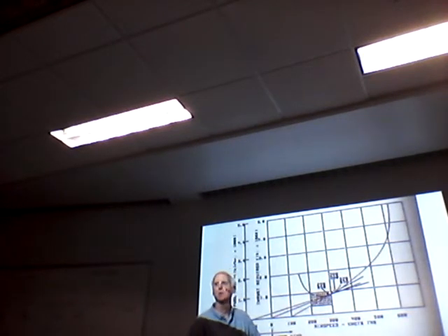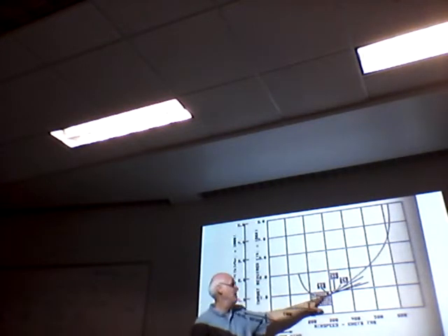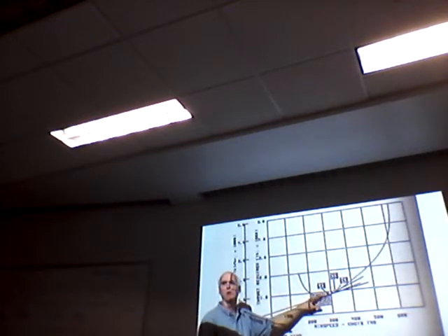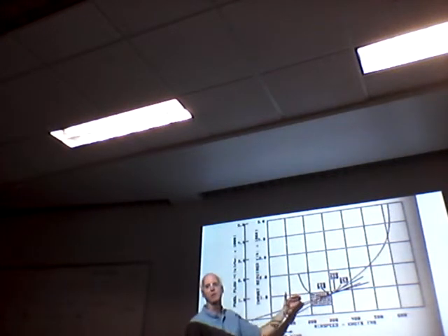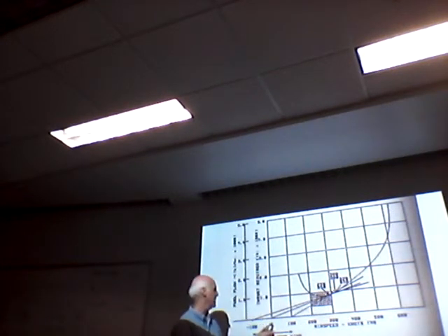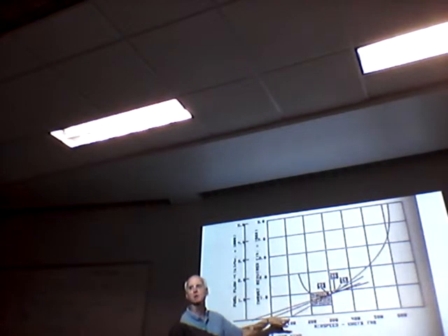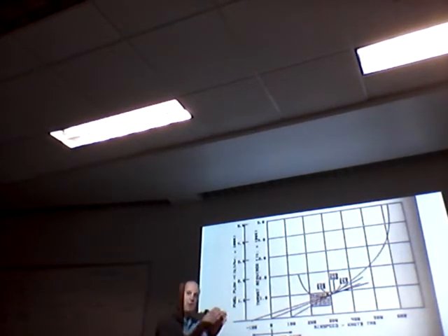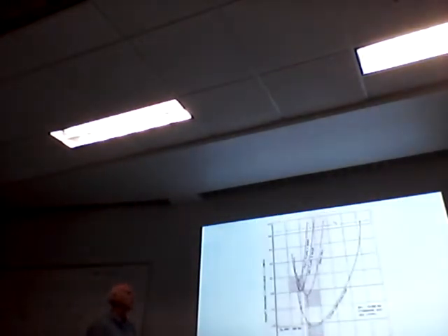Straight down, that would be the speed you would want to give as the answer. But if I have a tailwind, that tangent point is going to be further this way on the curve. It's going to be slower. I would take advantage of the tailwind if I can, but it's not the total amount. It's never going to be 100 knots faster or slower than the original speed. It's going to be a proportion of that. So you could derive that.